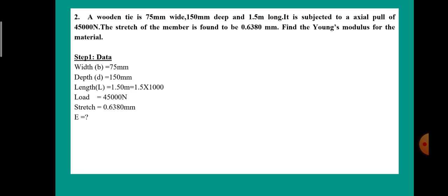The load they have given as 45,000 Newton, and the stretch, that is elongation, is equal to 0.6380 mm. Here they are asking to find out the modulus of elasticity or Young's modulus of the material. So the next step is the calculation of the area of the material.